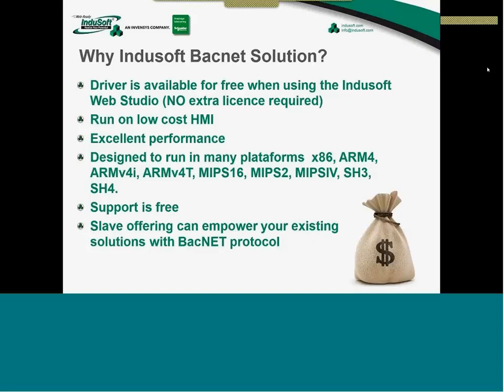The other advantage of BACnet is that you can use it as a low-cost gateway between, for example, Modbus and BACnet networks. Using the BACnet driver and the Modbus driver, or any of our drivers, you can expose your data as BACnet. You can also use the BACnet driver to get data and store it in a relational database using InduSoft.